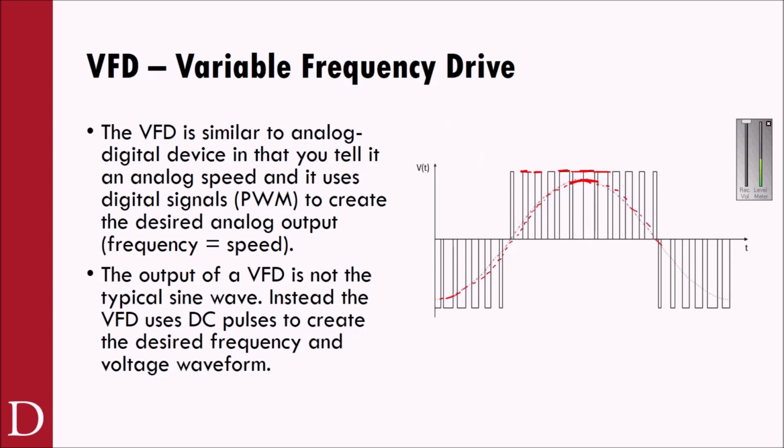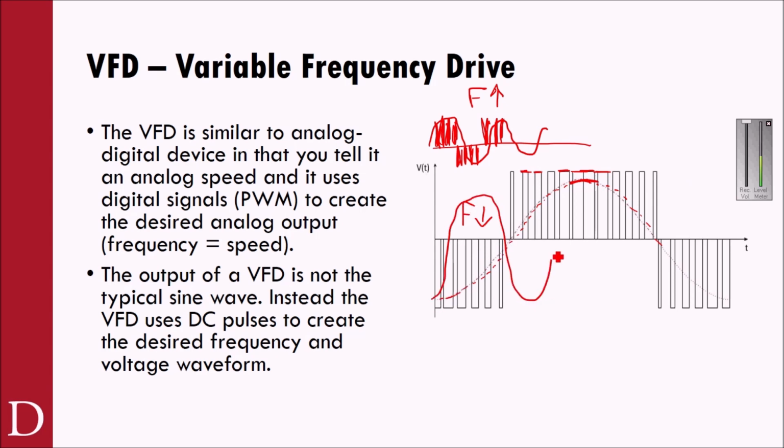Now what's interesting is, let's say you gap these differently, right? So let's say up here now you're turning on, and then down here you're doing it different. What you can see right here is I might have the exact same height of a waveform, but I'm doing it more often, so I'm getting a different frequency. So this is upping the frequency, and this would be downing the frequency. If I'm looking at the same amount of time, I can squish this thing together by firing faster, or I can spread it out by firing those transistors slowly.